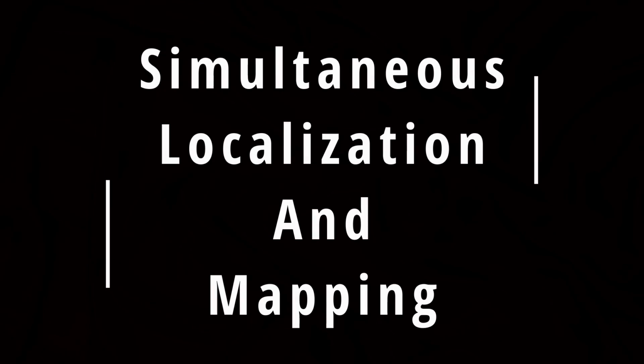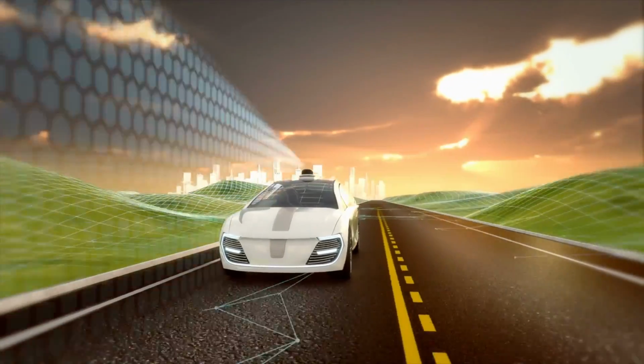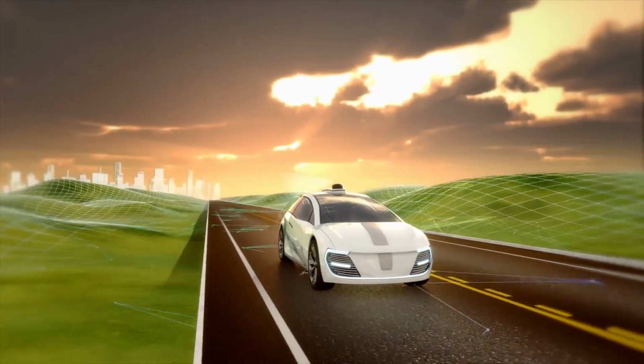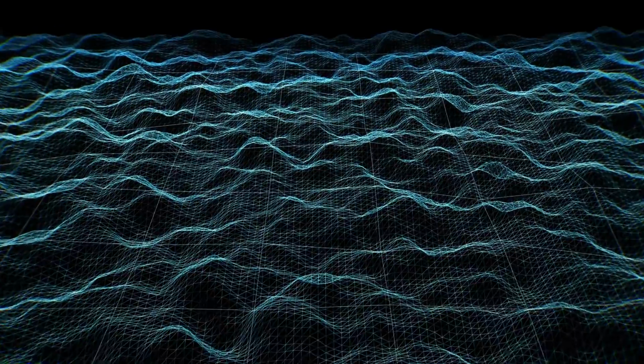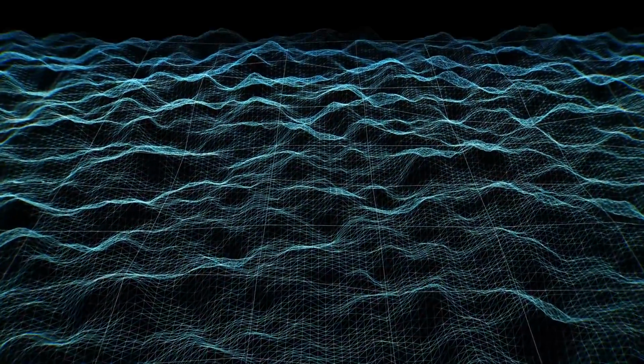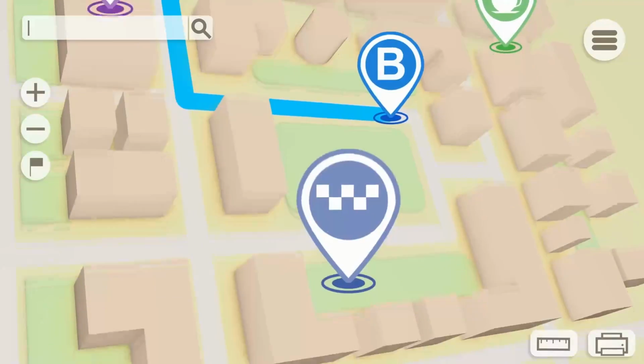So I will say that localization and mapping are commonly put into the same category, SLAM, simultaneous localization and mapping, but sometimes they'll be broken up. So the purpose of mapping is localization. Mapping is basically having your robot go out and collect the information of the space that you intend to run your robot in, so that you can establish and clean up sensor information that you can then store in a way that you can later load and be able to say, okay, I'm getting this current sensor information, I can compare that to the map that I previously stored and say, yes, this is where I think I am.